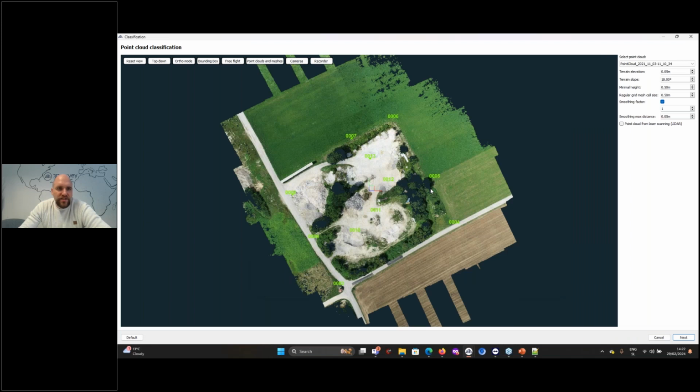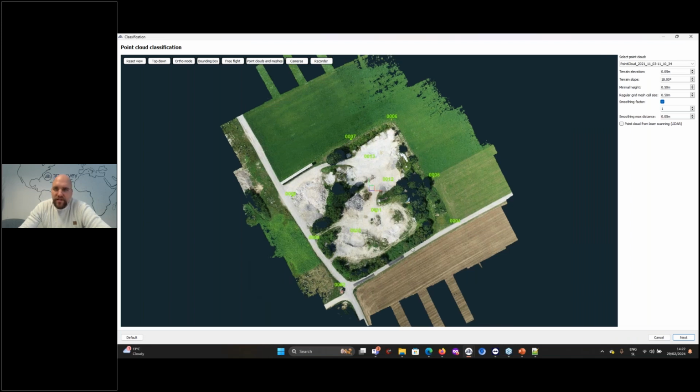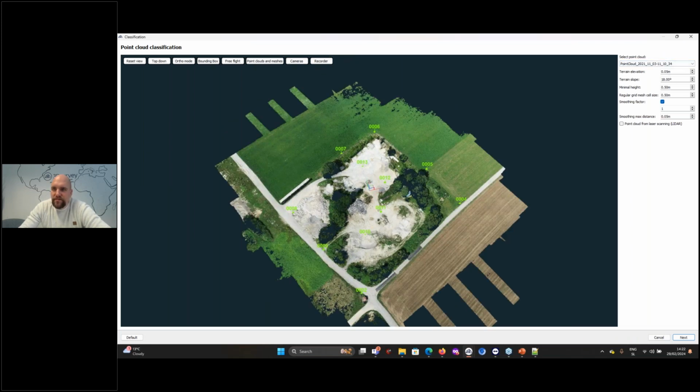And the classification in 3Dsurvey is semi-automatic. So here we have some settings for the classification algorithm. Let me explain it a little bit better. We are now classifying which points are ground points and which points are all the other points, because from the ground points we will be creating our digital terrain model and calculating contour lines. It's also needed when we are calculating volumes.